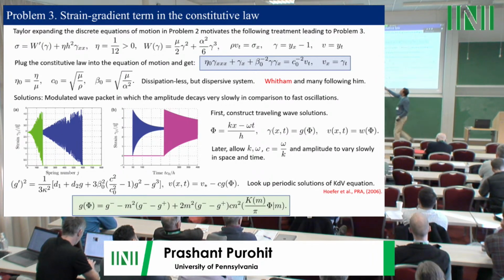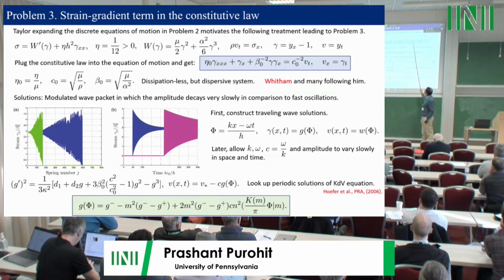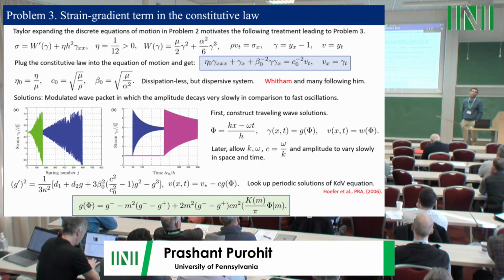You plug this constitutive law, the new augmented constitutive law with the strain gradient term, into the balance of linear momentum, and out comes that equation, which is the KdV equation. Okay? So once you have that KdV equation, then the machinery of Whitham's modulation equations can be used in order to understand what's going on with the dispersive shock waves, what's going on with these oscillations behind the front.